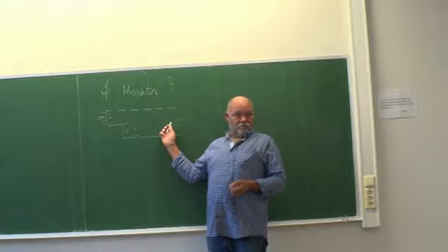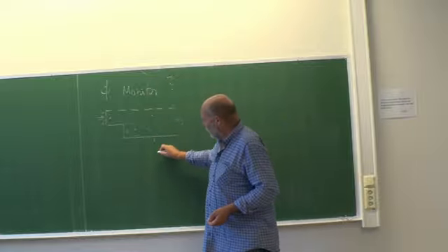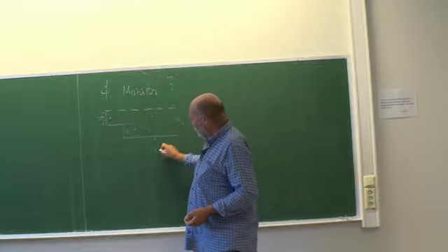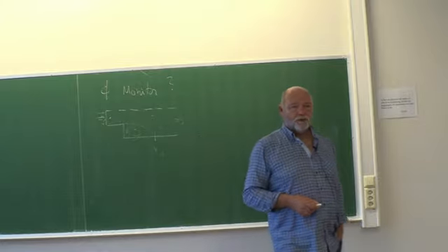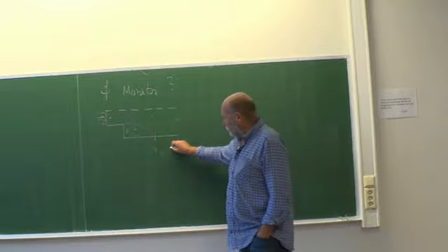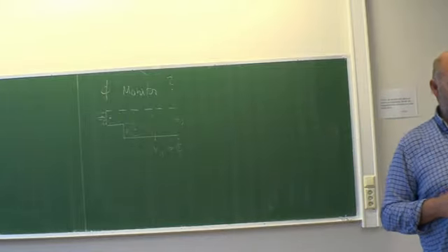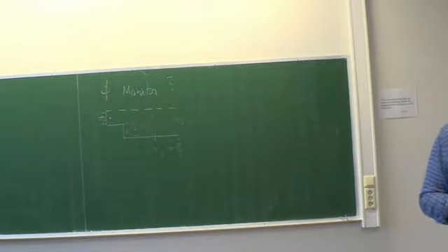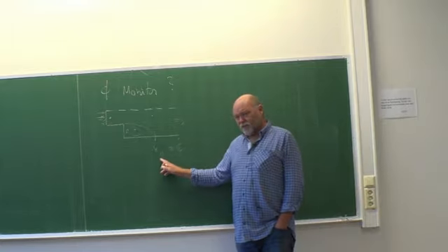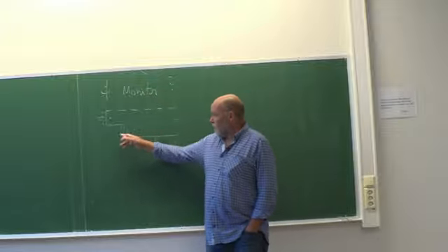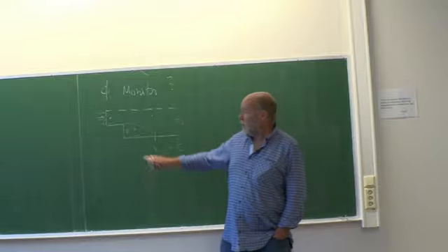In this article, with the description of the grid convergence index procedure, they have actually used this as an example. And what did they choose as a monitor? The reattachment length, XH, scaled with the step height. Why not? And as you saw from my solution for exercise 2, it's pretty sensitive. It changes all the time when you change the turbulence model or the mesh or whatever. So not a stupid choice. He describes the physics quite nicely. Good choice. Good monitor. Bad monitor.